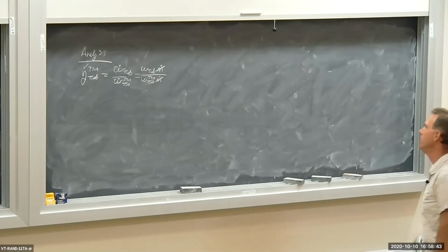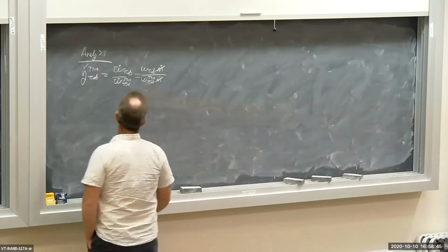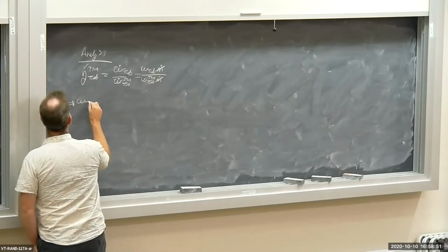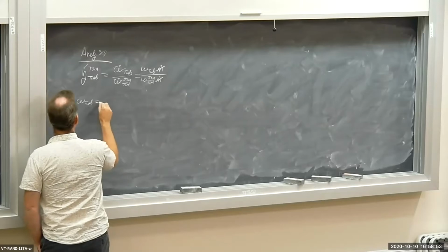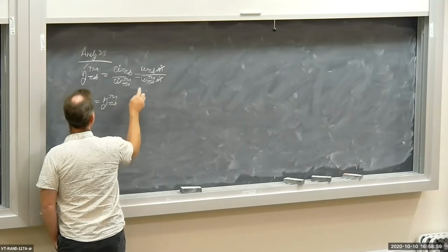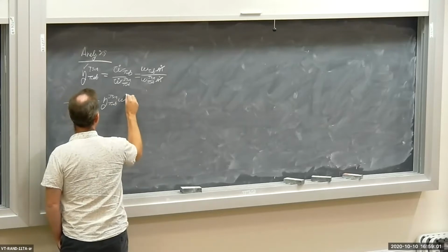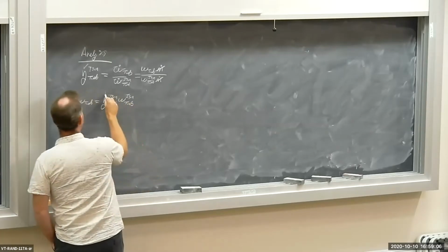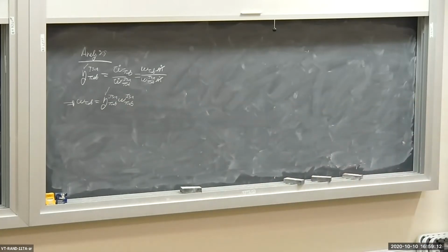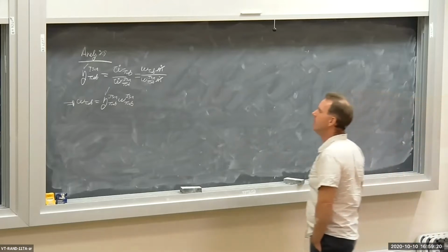Okay, so I want to get W turbine. So this means W turbine is equal to the isentropic turbine efficiency times the specific work of the isentropic turbine. I know the isentropic efficiency. I do not know the specific work for the isentropic turbine, W isen turbine. So I need to find that. Well, how do I find this?